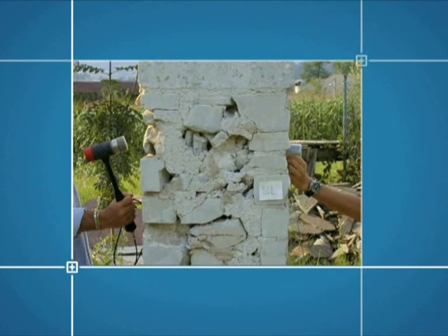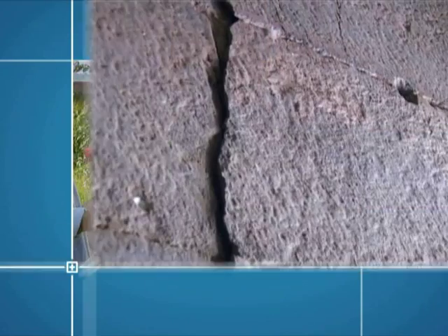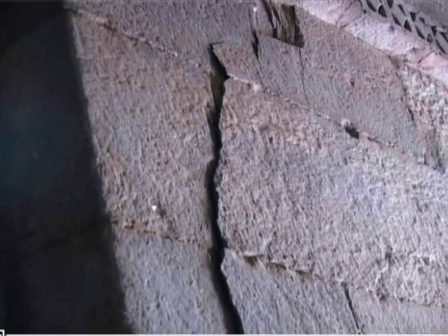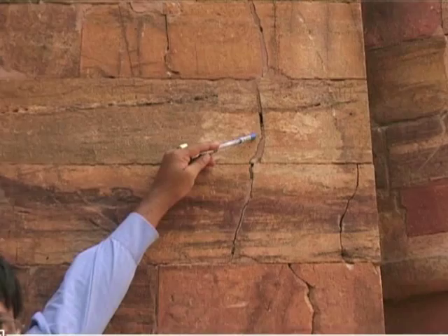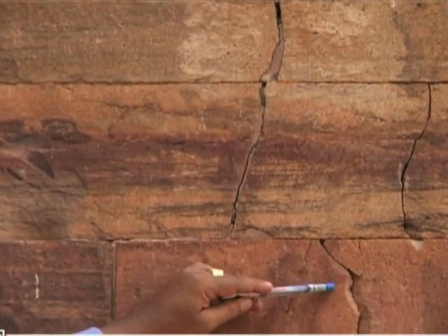Sonic tests are applied for measuring the transit time of elastic waves in masonry structures. This transit time and the calculated sonic velocity provide information about the quality and consistency of the masonry element under investigation. The velocity is influenced by the composition of the masonry, as well as by the presence of inhomogeneities, voids, and deteriorated areas.